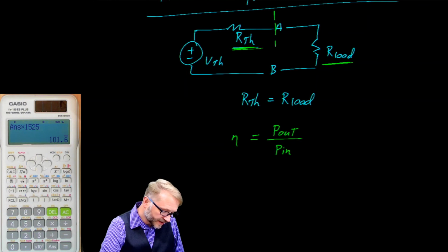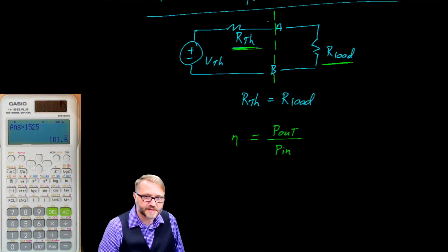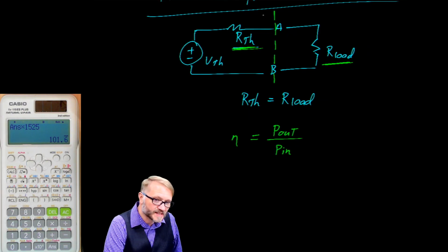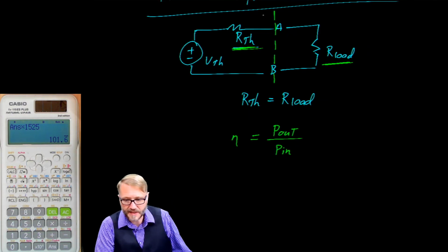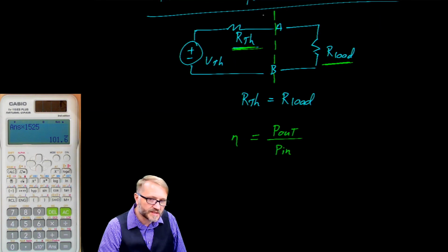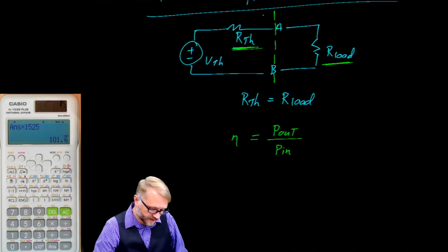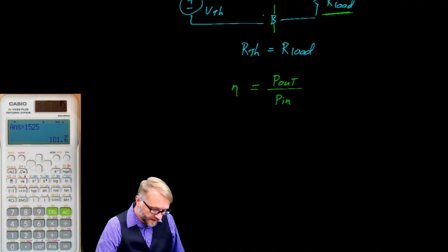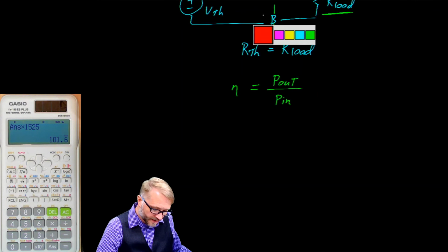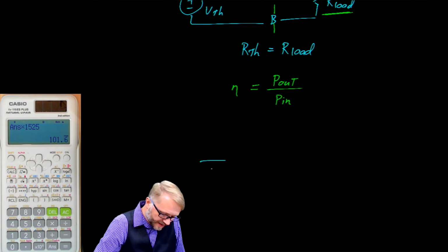And again, if you look at this line here, this line is the demarcation point. Everything to the left is inside the power supply and everything to the right is outside. So that means your power supply is going to get very, very hot. Half of the power is going to be burned up within it. And you think about that, it's like, that's just a disaster waiting to happen.